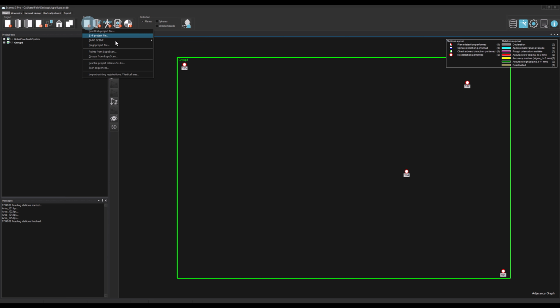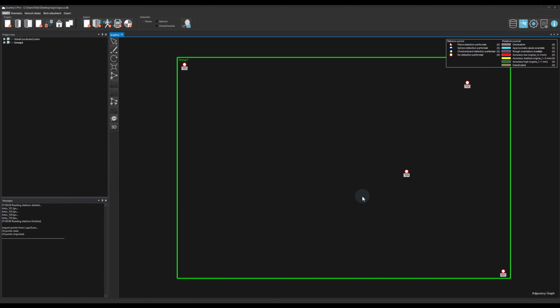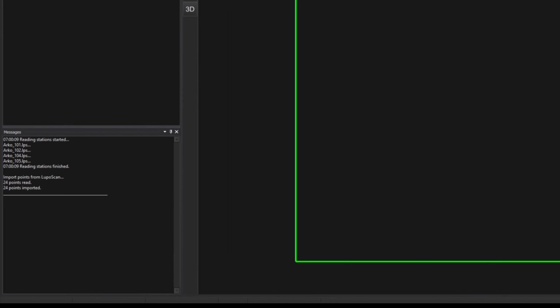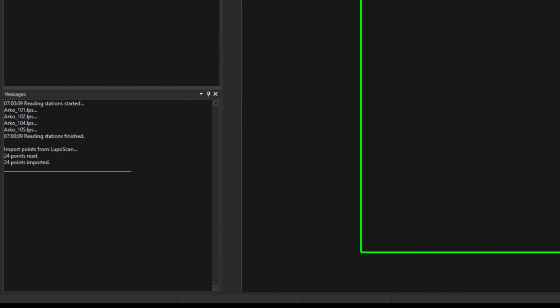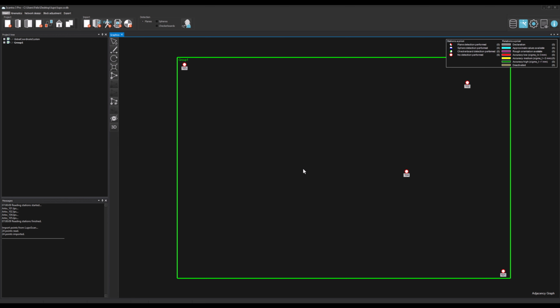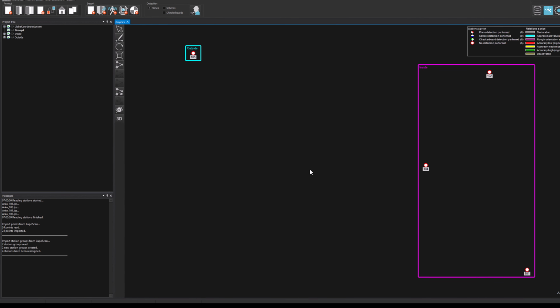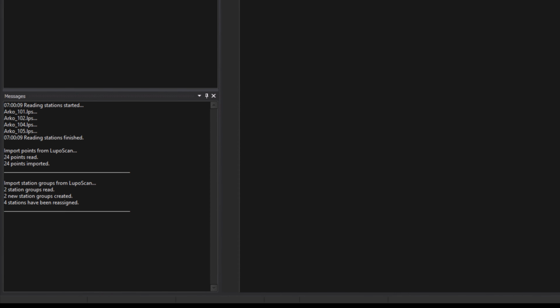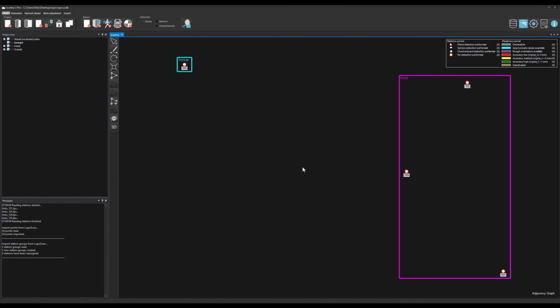Files with the suffix lps.ori contain points that were digitized in the scanner's local coordinate system. Files with the suffix ref contain geodetic reference points. Local and global points with identical identifiers were already matched in LupoScan and hence can be matched in Scantra by using this information. Groups can be associated to individual scans by importing ini files under groups from LupoScan. In contrast to Scantra, individual scans can be associated to several groups in LupoScan. Hence, Scantra will associate a scan to the first referenced group in the INI file.